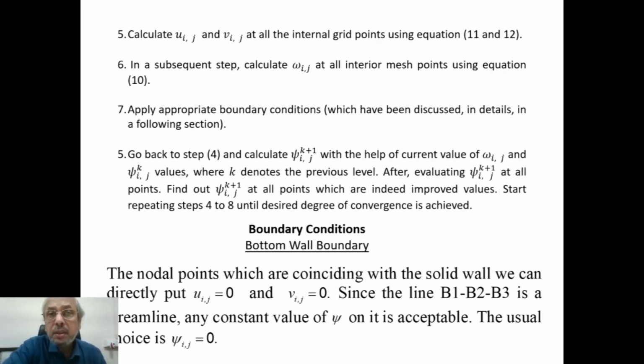We are not marching in the time direction, but the way the flow field is evolving is almost like marching in the time direction. That is why such procedures are called pseudo time marching. Pseudo time marching, not actual time marching.